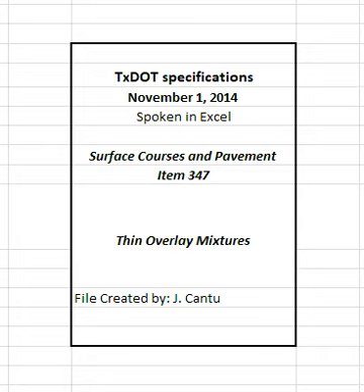2.5 Tack coat. Furnish CSS-1H, SS-1H, or a PG binder with a minimum high temperature grade of PG 58 for tack coat binder in accordance with Item 300, Asphalts, Oils, and Emulsions. Specialized or preferred tack coat materials may be allowed or required when shown on the plans. Do not dilute emulsified asphalts at the terminal, in the field, or at any other location before use.